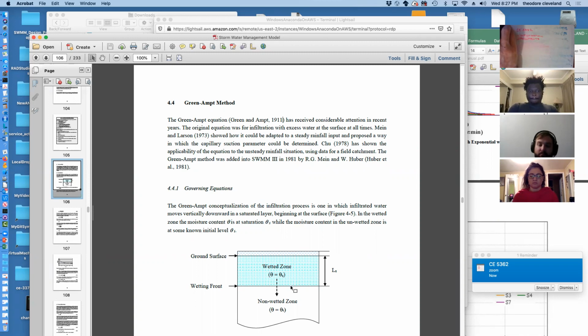And then at the wetting front, the total head is minus the distance into the soil, plus 0 for the liquid pressure. And so we take, let's call this depth cap H, we take cap H minus a minus Z, and then divide by Z. So we have cap H plus Z over Z gives us our hydraulic gradient, and that changes with time.